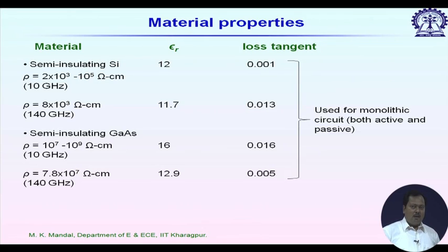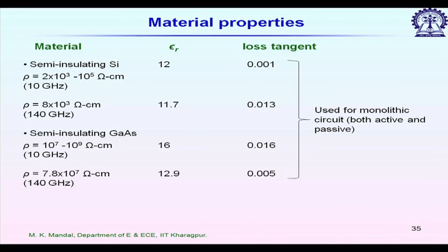First of all, silicon or germanium, and typically when we consider N type or P type materials, they are semiconductor materials. So, they come with a finite sigma value. So, it is very lossy. We can't use semiconductor materials as metal, or even as dielectric, because if we treat the semiconductor material as dielectric, it will be very lossy. Already at millimeter wave frequencies, we have many sources of loss. We do not want to increase the loss further.